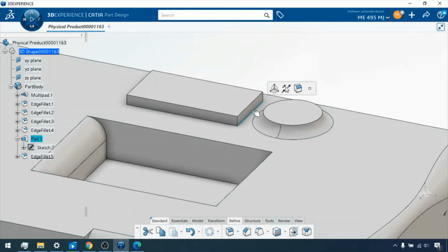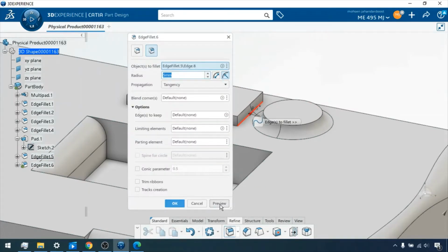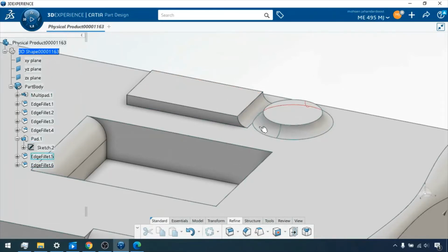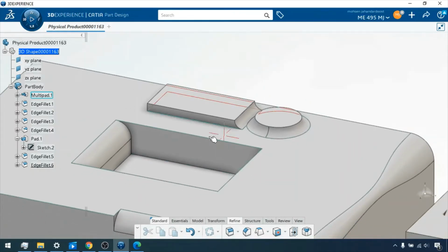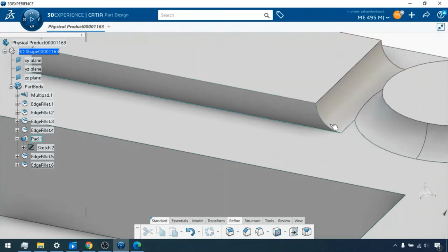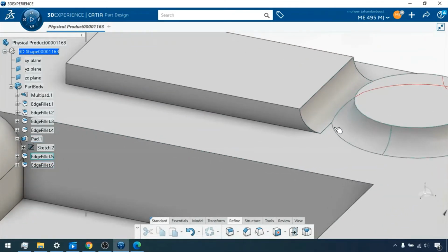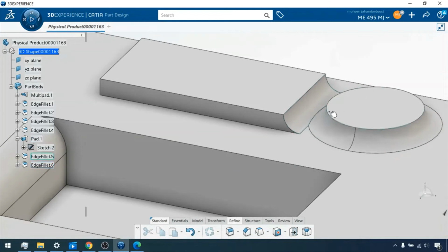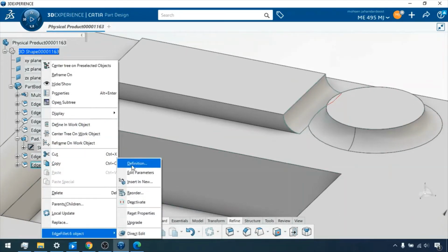So now let's say that I want to create another fillet for that face. So when I do that, with 5mm, just select the minimum. So here, let's say that I create another fillet here, and you can see that these two fillets meet each other, and then you can see here the software automatically creates the calculation between these two edges. So the straight line, if I don't have this fillet, goes further inside, but now the software automatically calculates the relation between the previous fillet that I had and the new one.